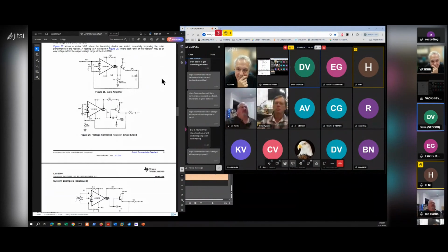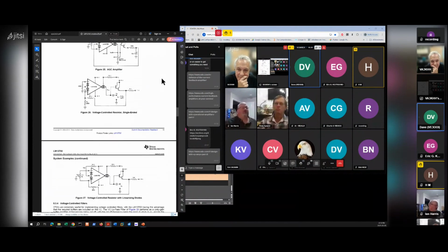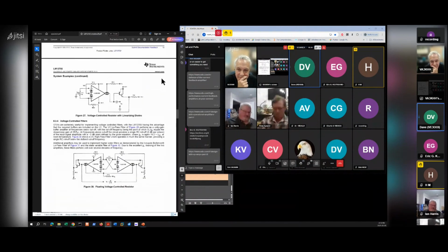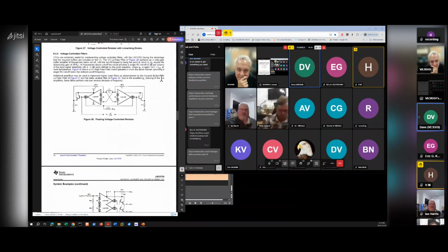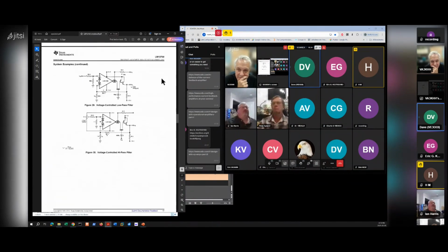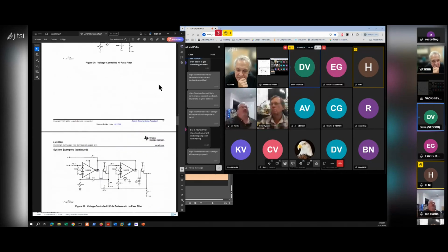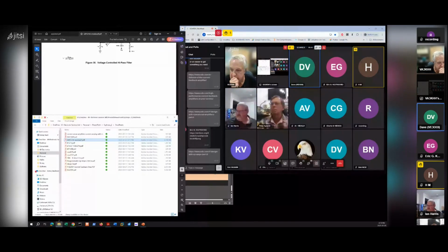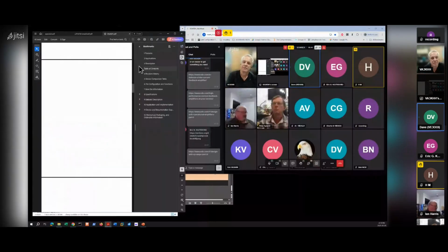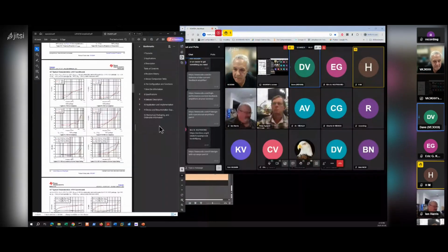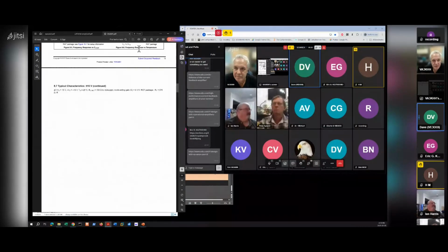They'll say it's good out to like 300 megahertz, and I found at like 30 megahertz the gain starts dropping off, or at 40 megahertz it starts dropping off. So I've never had much success with those amps. So I don't know if there's a trick or something.